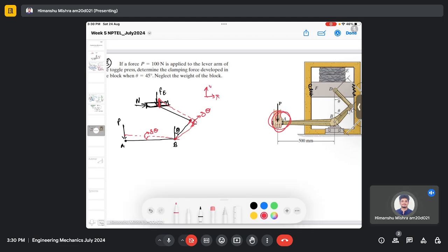If I define the coordinate system x and y, then there is a virtual displacement in the y direction, which I can define as yd, and there is a virtual displacement in the y direction along the force P, which is, let's say, ya. Okay, so until now we know that we need to define the virtual displacement because we need to use that in the virtual work expression, and then the summation of it is zero because the body is in equilibrium.